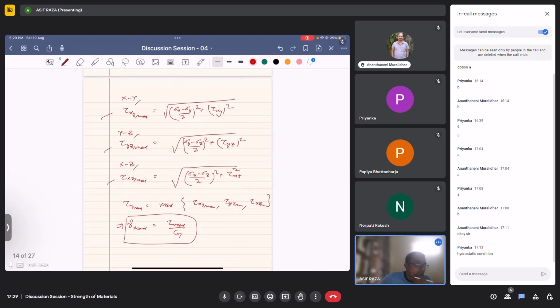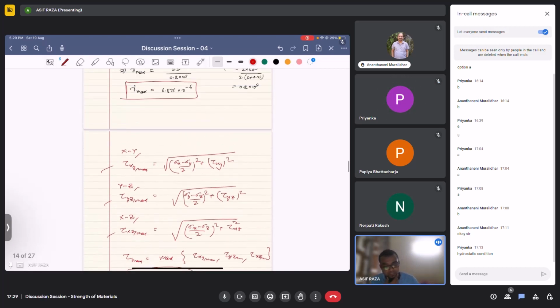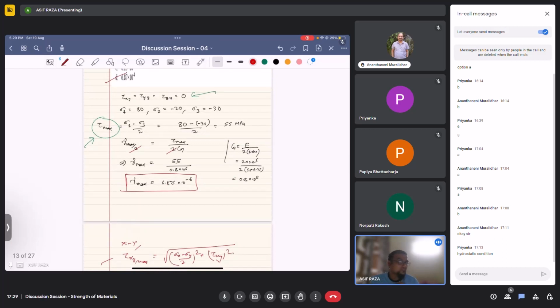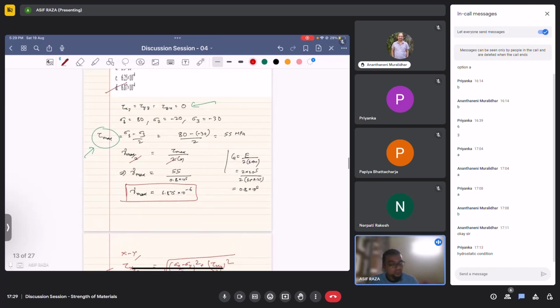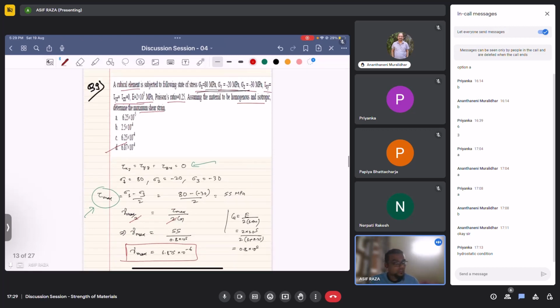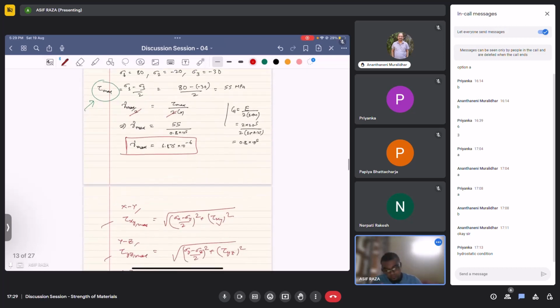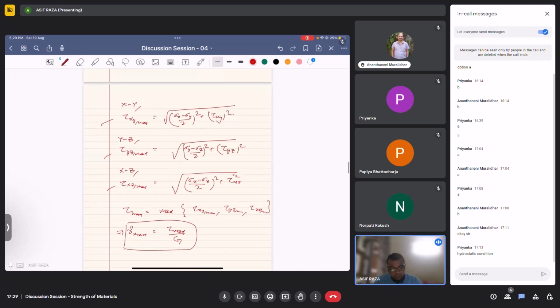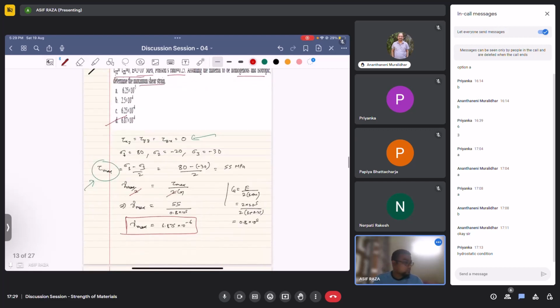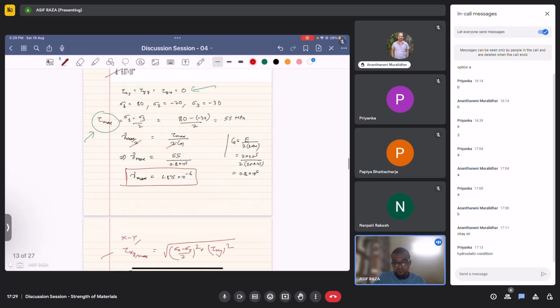I think what Priyanka was saying pertained to this direction. Is it, Priyanka? Yes, sir. Okay, so your approach is quite correct. But in this case, since the shear stresses are 0, the stress values given are principal stresses, so we can directly find tau max easily. No need to go through the pains of finding the square root and all. I hope this question is clear for you all. Let's move on to the next question.